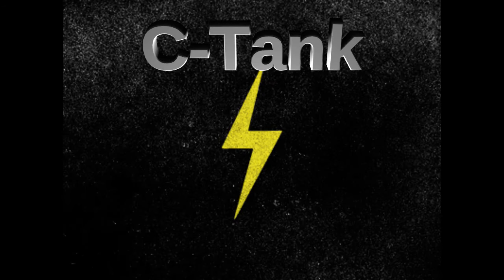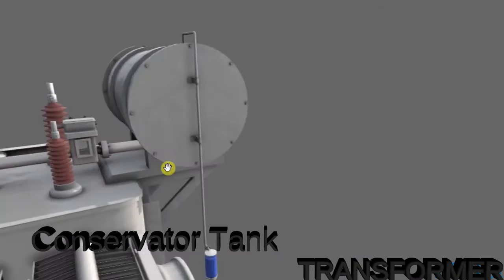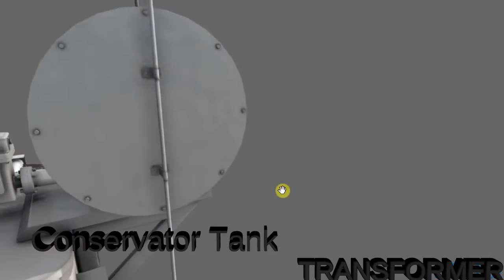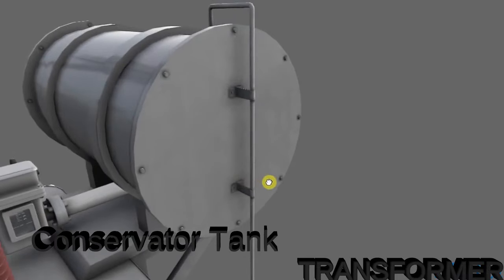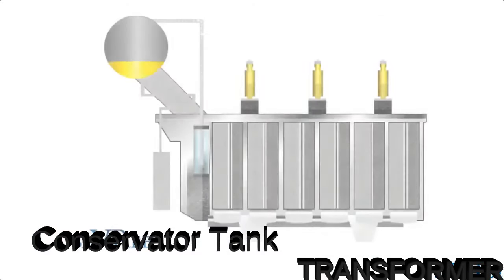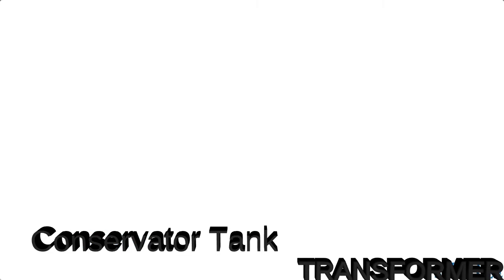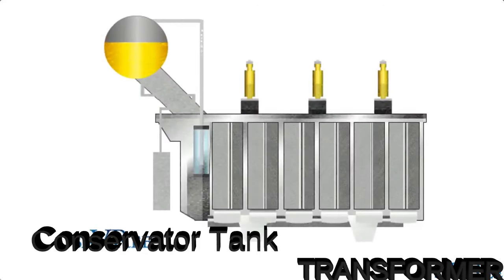Conservator. Equipped with transformers of rating 500 kVA and above, it is a drum containing transformer oil and mounted at the top of the transformer and connected to the main tank by a pipe. When the transformer is heavily loaded, the insulating liquid will heat up and expand upwards. When the transformer cools down, the insulating liquid also cools down and the level of the insulating liquid will drop.